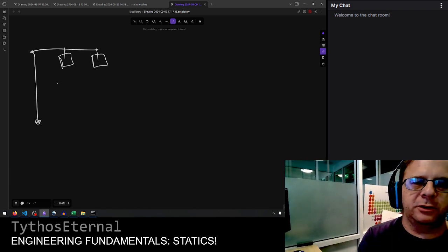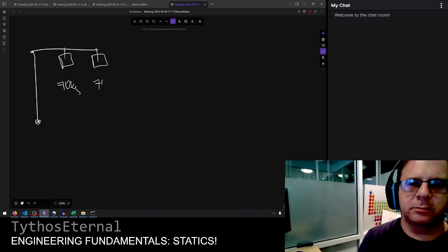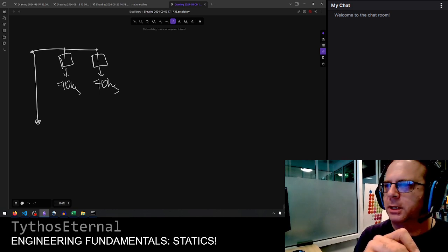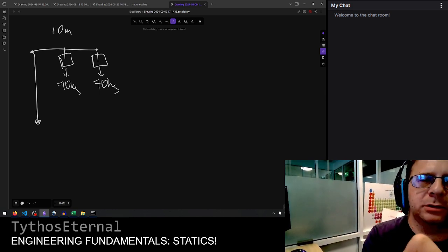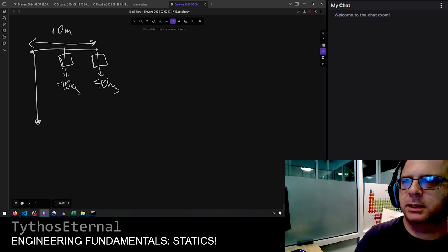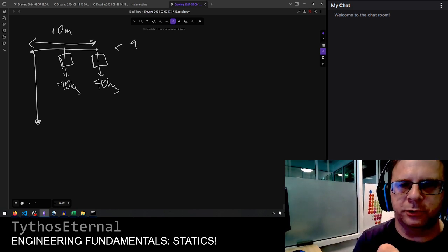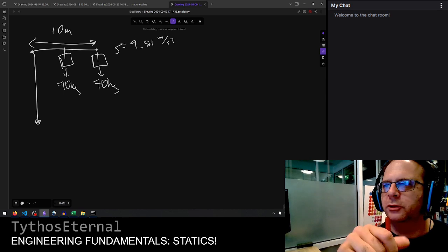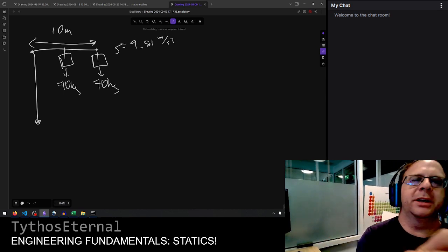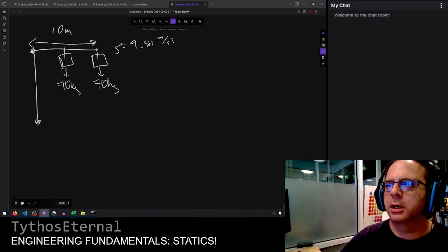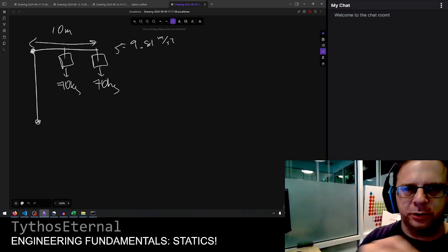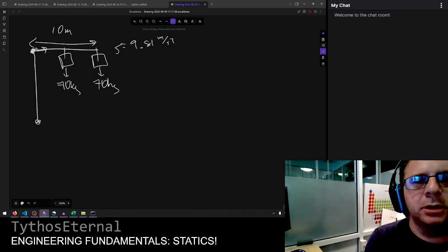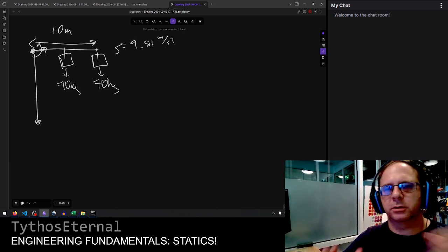So let's say these each weigh 70 kilograms. So we know their weight is applying some force. That this beam is 10 meters long. And just for shiggles, we'll assert specific precision for gravitational acceleration. So the question here is what moment has to be supported here, right, at the joint. So if this is a static system, again, let's posit our frames. So we'll say origin here, positive x to the right, positive moment right-handed about that pivot.